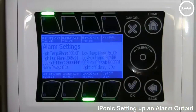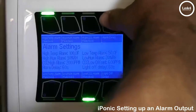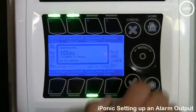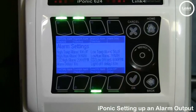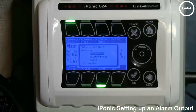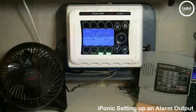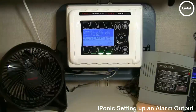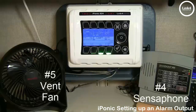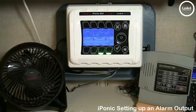Simply hit OK. Now for testing purposes, we're going to go ahead and change the alarm delay. And we're going to change this alarm delay to be 10 seconds. Hit OK. And now what we're going to do is hit the home button and save our changes. Now let's put this alarm to the test. We have a vent fan plugged in on output number 5, and we have a Sensaphone hardwired to relay output number 4. The output we have programmed as an alarm output.